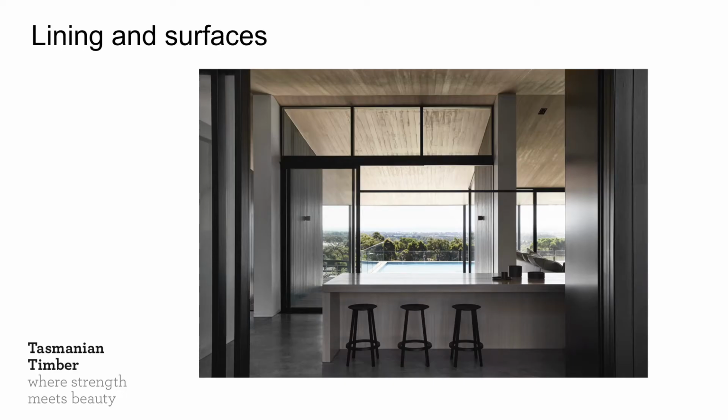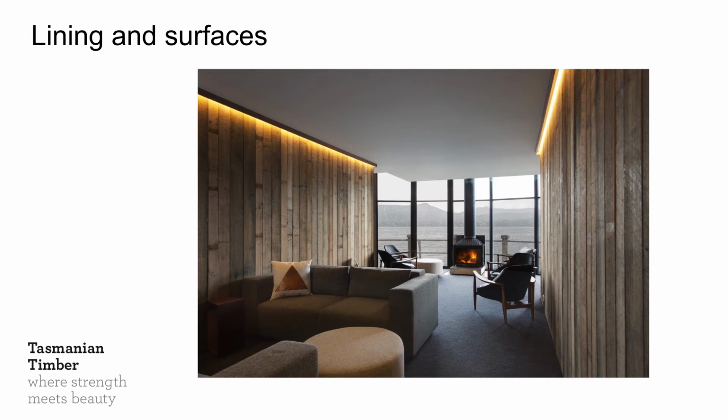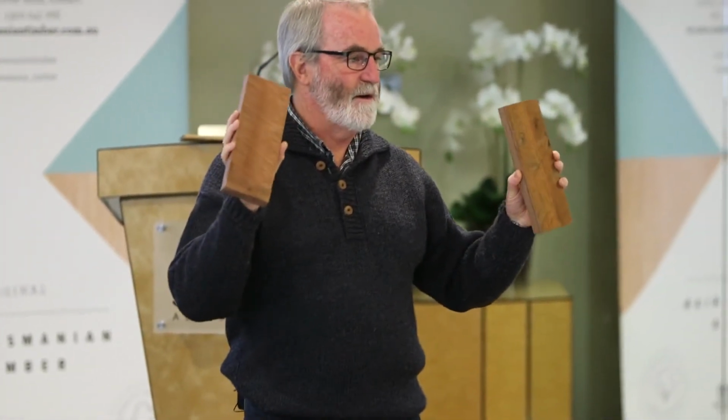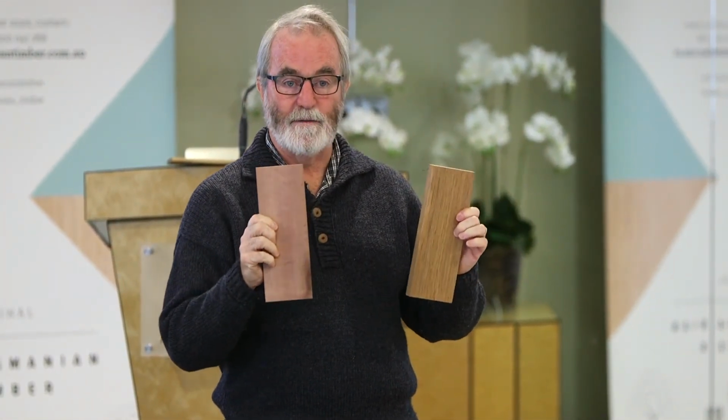Linings and surfaces then become a stock trade. I've just got a series of images here from various producers, various projects. This is with board as a ceiling. Here's with board. I think this is one of the extensions to the pump house project at Lake St Clair. So these are boards that have not been planed, not been dressed all round. You can still see sticker mark on the board. So you see this little shiny bit, that's where the sticker had gone through, and you've got that mark on the board. And you'll see with most of these pieces we've actually got the rough side on one and the dress side on the other.